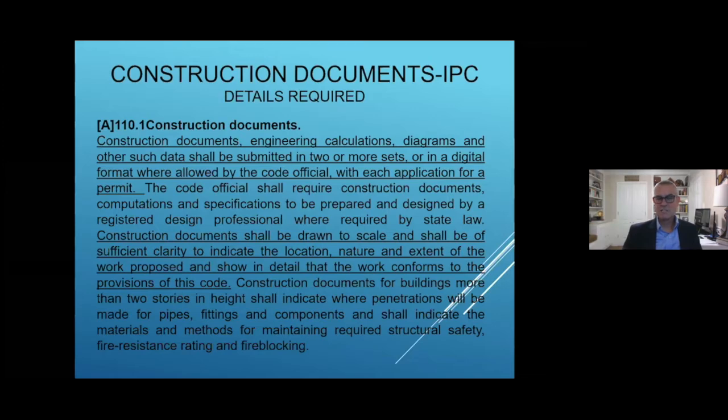And things like locations become extremely important, like the location of an underground storage tank or aboveground storage tank, for example, might be something that could create a hardship when you're doing the installation. You probably want it closer to one area. There might be other things in the way, underground LP tanks, other oil tanks, for example, who knows, whatever else is around. That's why it's critical that the drawings include all those types of details, so you don't leave out something like that, and then you get a new system installed and you call for an inspection, and the inspector shows up and finds out all of a sudden there's another tank underground that was never identified, and then things have to be shifted around. And again, construction delays, that's what I'm trying to help avoid with this presentation.